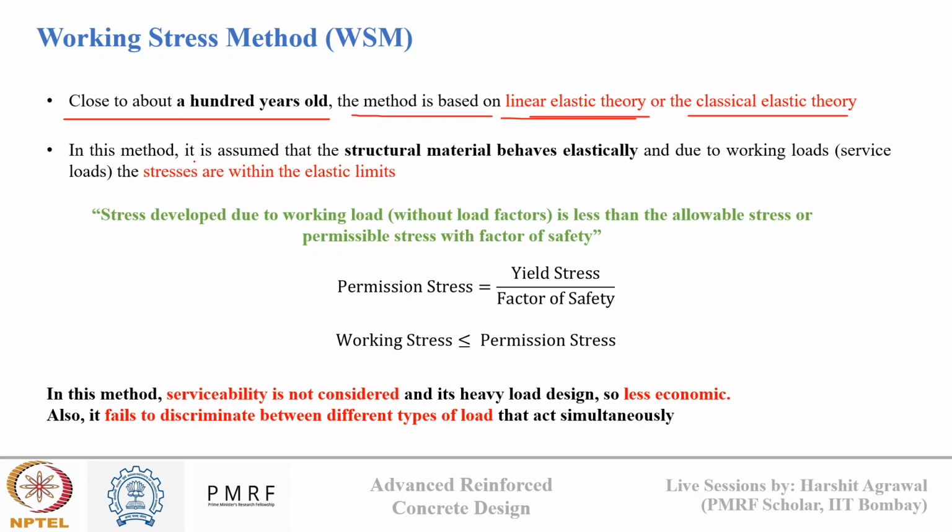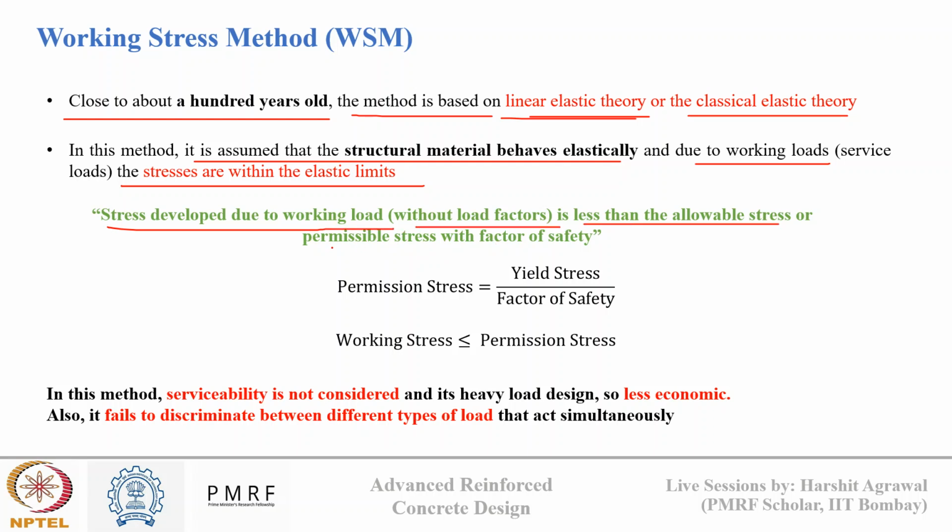So in this method, it is assumed that the structural material behaves elastically, and due to working load, the stresses are within the elastic limit. Design based on the working stress method ensures that stresses developed due to the working load are within a permissible limit using a safety factor. You can see here the definition that we have written: stress developed due to working load without any factor is less than the allowable stress or permissible stress with safety factor. So this is the equation that we are talking about.